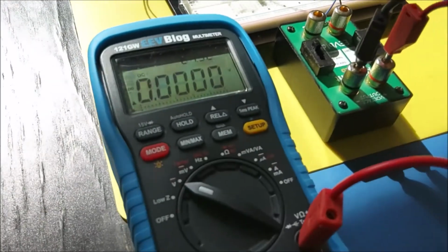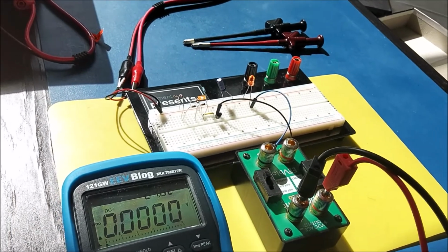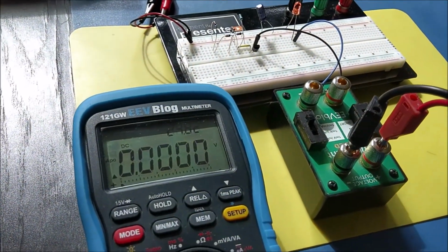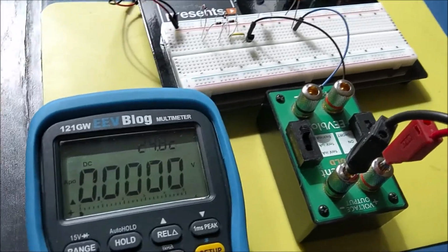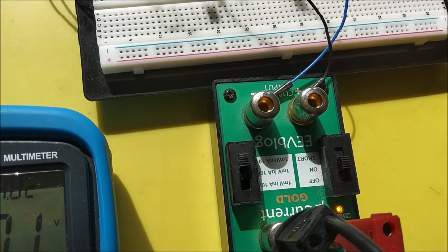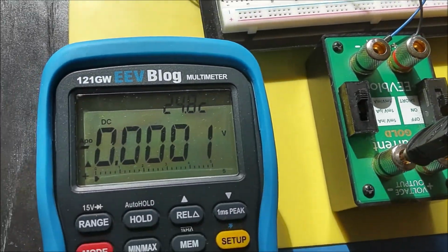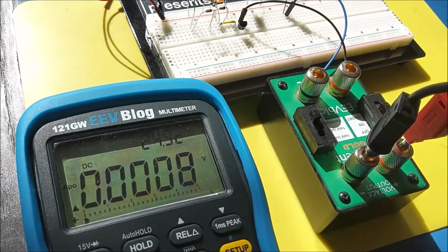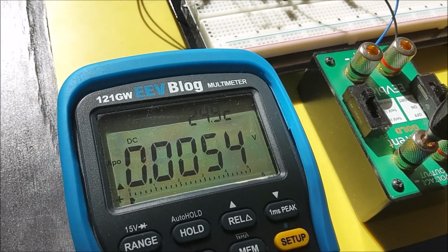We will check this in this setup here. I will switch this on in real life and see what happens. Whenever we see a millivolt on this meter, that should represent 1 milliamp in the circuit, because I have set this device here, a microcurrent, to 1 millivolt per milliamp. So I'm going to turn up my power supply. It's 10 volts. Let's have a look at what it says here.